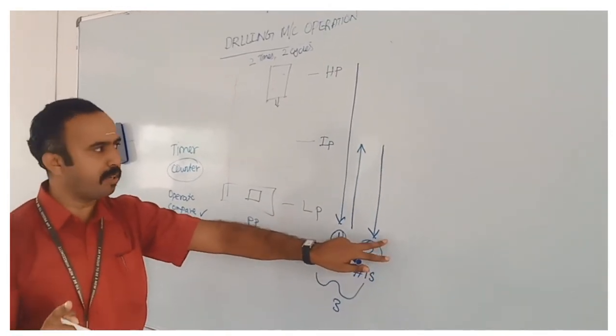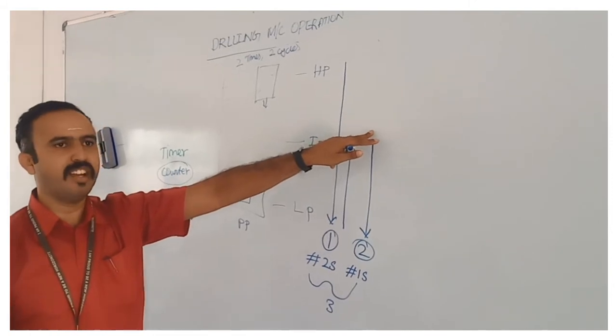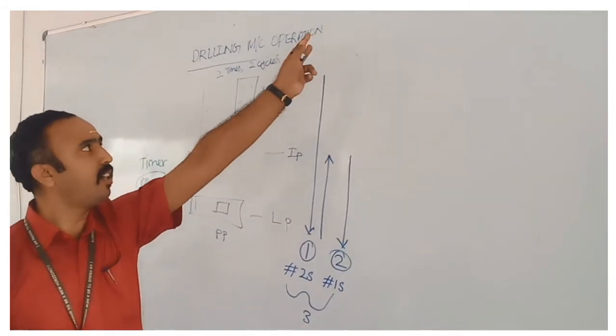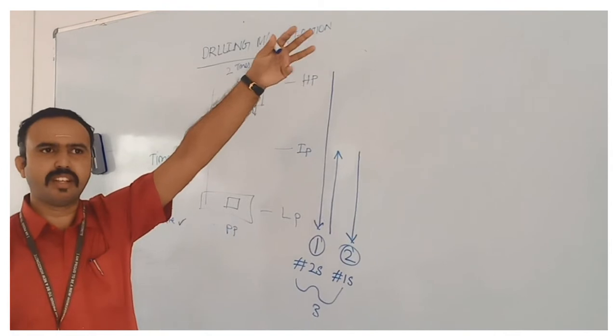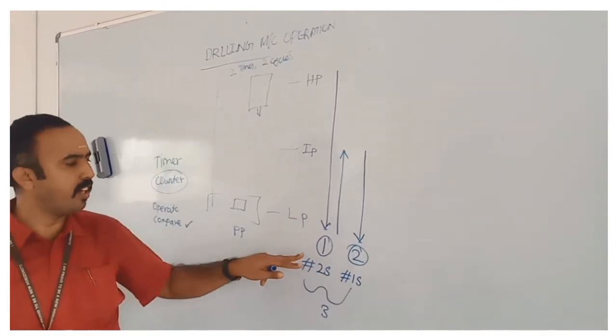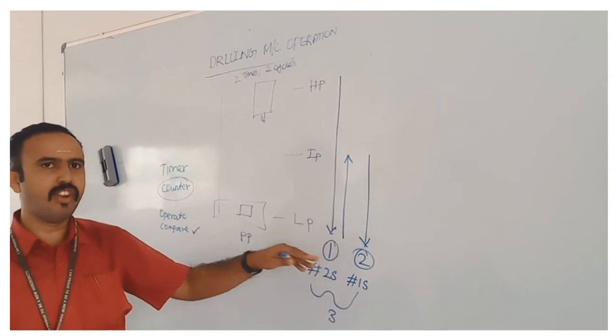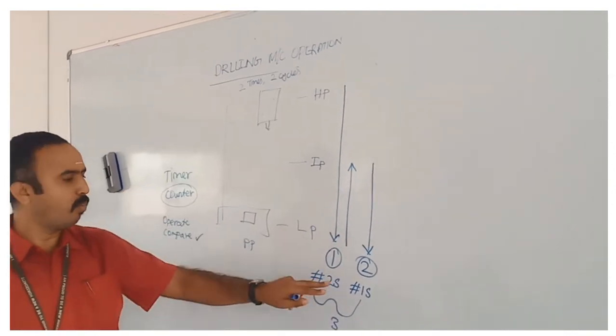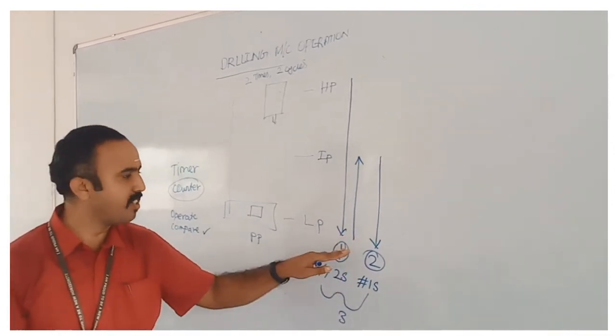If it is not completed, once again go to the intermediate position. If it is completed, it will go to the first position, that is the initial step, so the process will end. But as of now, only 2 times it is done. We have to do it for 4 times. So only half the condition is satisfied. Now it will check for the cycle.